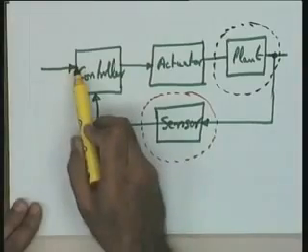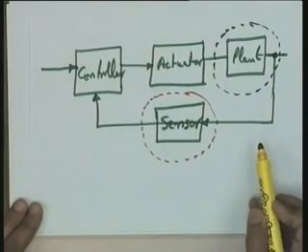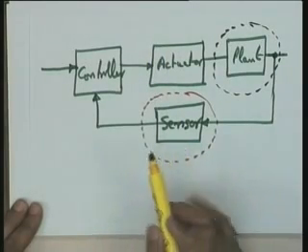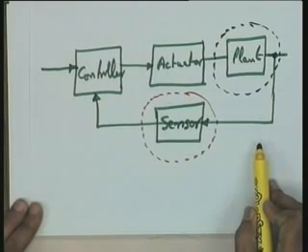You require amplification of that to make it compatible with the standard input signal or to make it usable by the controller hardware. So, suitable amplification or conditioning of the sensor output will be required, and that also you will do.